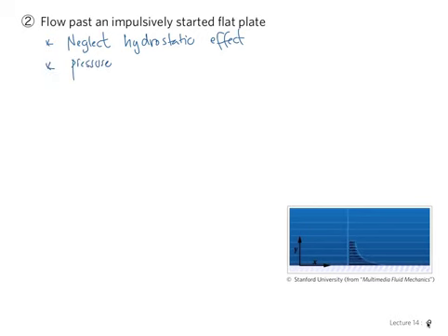But obviously, when I look at this picture, it's not steady. This is the situation: the flow starts from 0, and there's a flat plate that starts from 0. If everything is 0 at the beginning and the plate starts moving, because of the no-slip boundary condition, the first layer of fluid is going to move with the plate, but the rest of the fluid slowly is going to be accelerated by the effect of the viscosity.